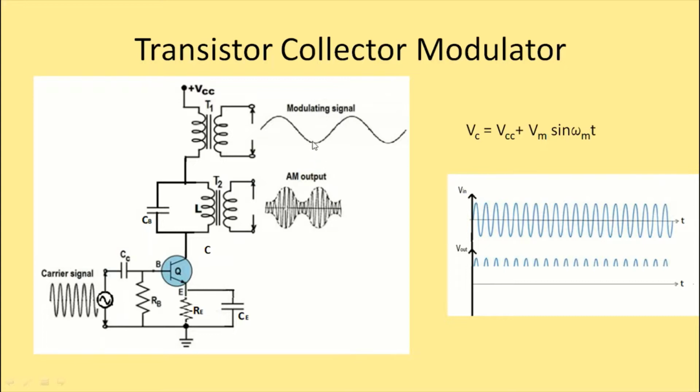Now say for example, from this minus 5 volt, we go to a point somewhere here which, say, is measuring minus 3 volts. Okay. So now a minus 3 volt AC signal is coupled to this side. So that means here the total voltage now will be VCC minus 3 volts. So when compared to the previous value of biasing, which was VCC minus 5 volts, now it is VCC minus 3 volts. That's it. So observe, the biasing of the transistor is now increased by 2 volts.